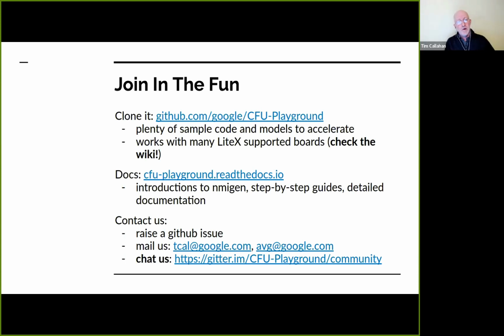Unfortunately, I don't have hard numbers for you, but I will say I'm just as interested as you are, because as with all tinyML apps, power is one of the top, if not the top concern. So we are very concerned about power. And I mean, you can play some of the same games that happen inside microcontrollers. You can turn off the power to certain regions that you're not using. I guess a very hand-wavy answer is if you can exploit the parallelism of the FPGA by doing a lot of stuff in parallel but slower, that's usually a win for energy. But on the other hand, of course, there is an FPGA tax of making things configurable. That just means you have more switches to go through. There is more capacitance on the connections.